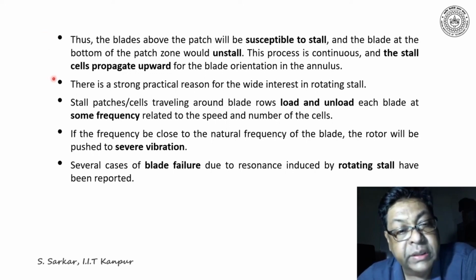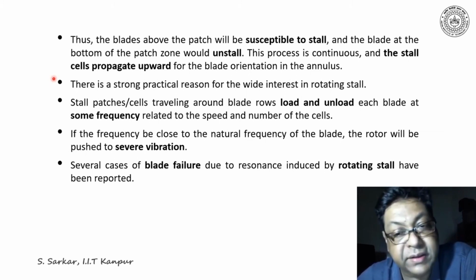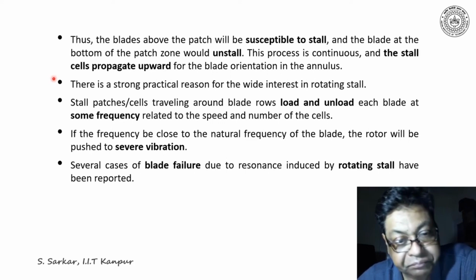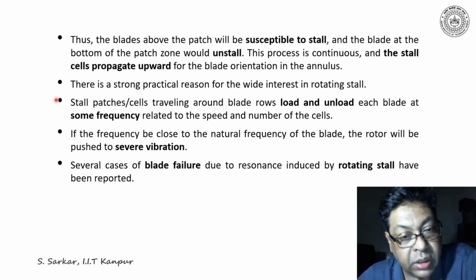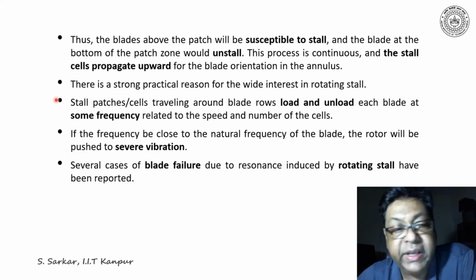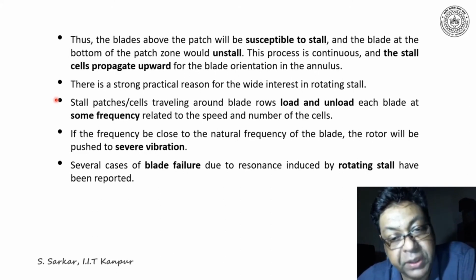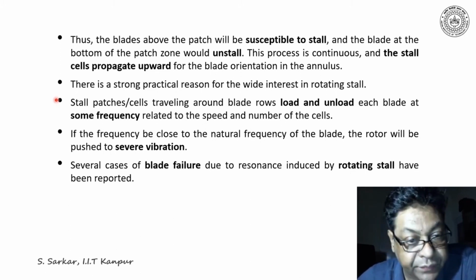Furthermore, there are strong practical reasons for the wide interest in rotating stall. Stall cells or patches traveling around the blade row load and unload each blade at some frequency related to the speed and number of cells in the annulus.